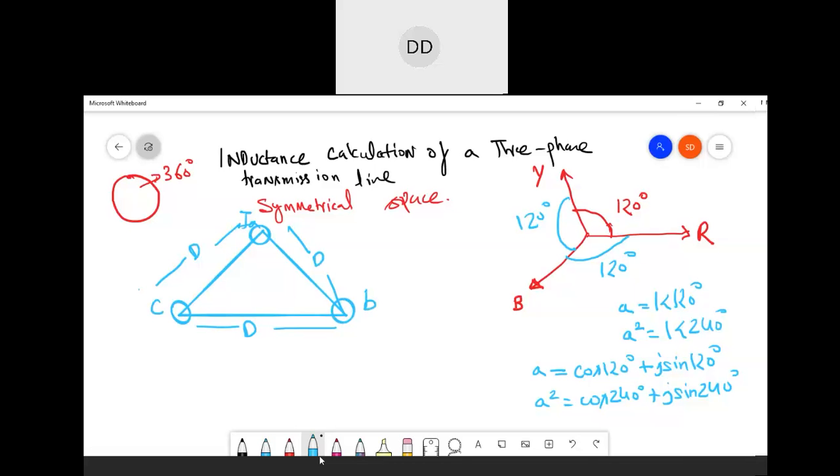For the conductors in an equilateral triangle, the sum of the currents entering and leaving for a balanced three-phase circuit, that would mean if Ia is the current entering plus Ib plus Ic, you can write it is equal to 0 in this case. So only when the conditions are balanced. Balance means the currents are the same in all the phases, and the load which you are going to connect, if at all you are connecting any load.